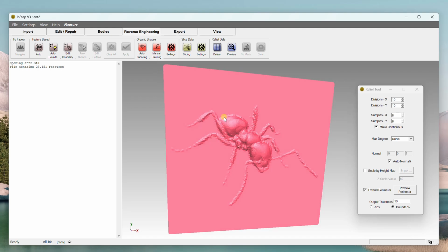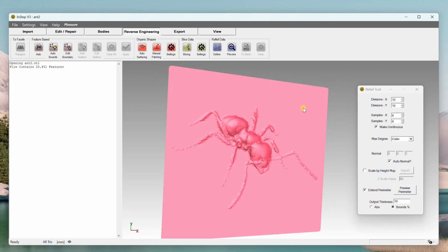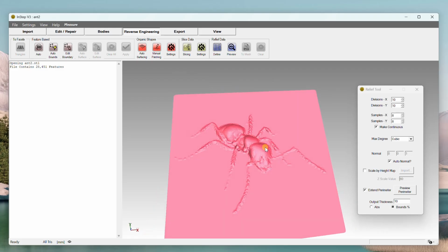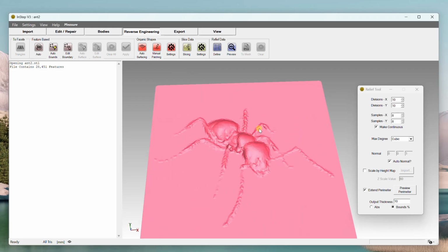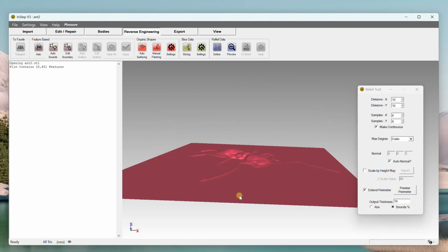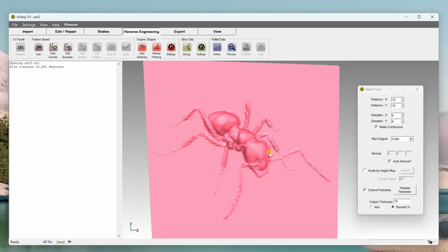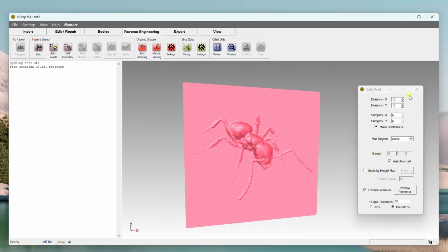But generally it should be parallel to the XY plane. It does have a way to deal with non-parallel items, but I recommend that you always keep it as flat as possible, and if possible also keep the Z coordinate at 0. That's generally the way it's expected to work.